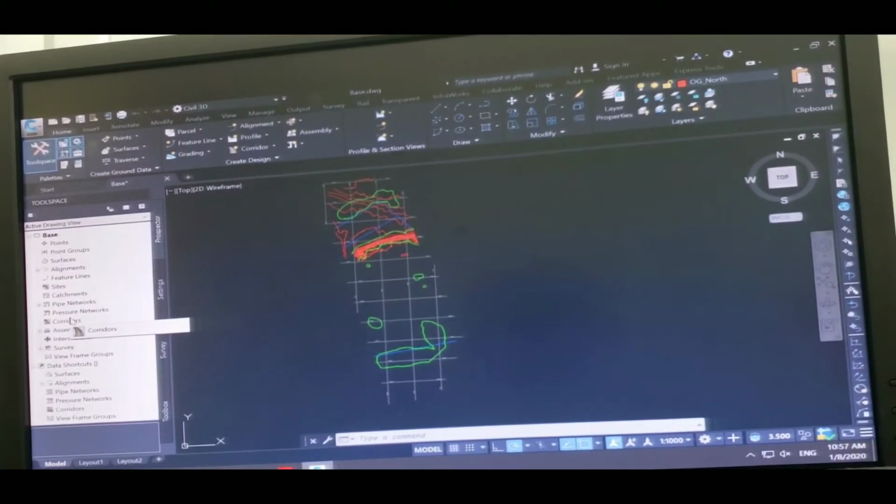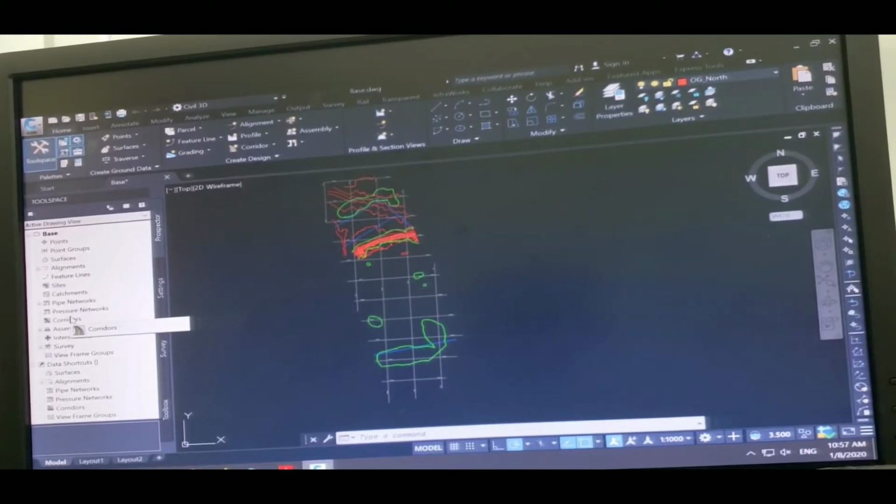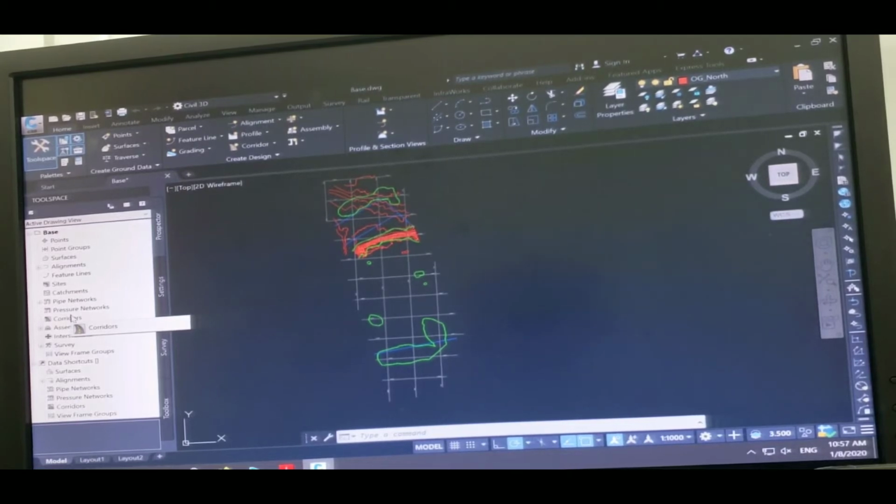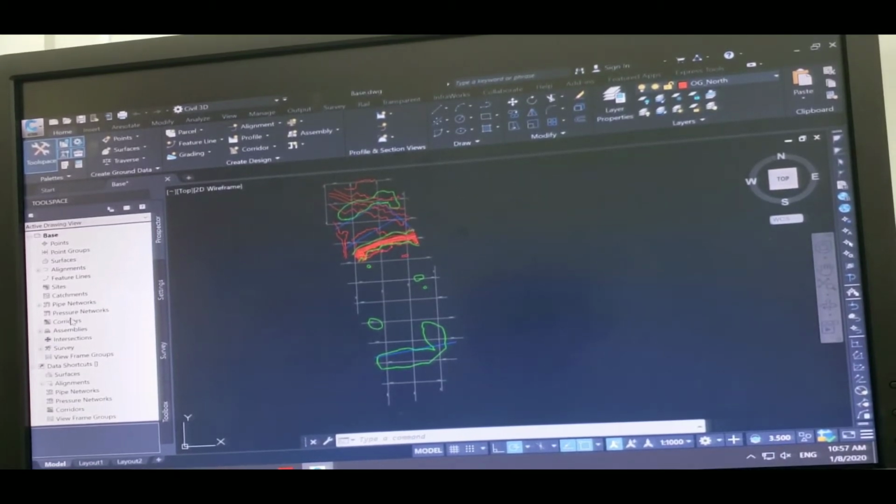That means that whenever you are doing a curve, the asphalt may be tilted this way to help the car do the curve. Have you guys ever experienced this when driving? When you're doing a curve, actually the asphalt will do like this to help you do the curve. So you will learn how to do that by hand, but you'll be doing it here as well. And AutoCAD will say, okay, this is the profile of the road. It will automatically calculate for you what are the changes that need to be done to make the super elevation for you. Okay?